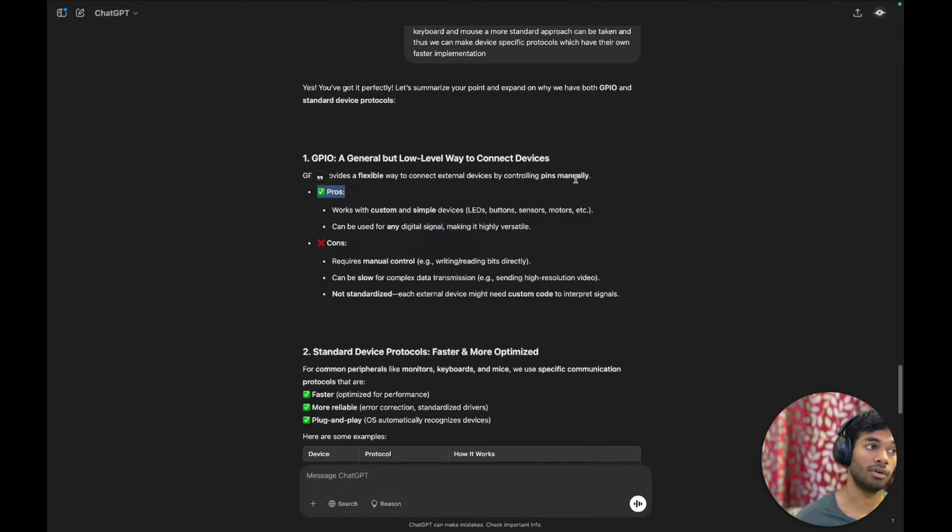Yeah, motors. I can use a GPIO which is embedded on a Raspberry Pi to control a motor, and that motor can be connected with a string which is wound around my doorknob, and whenever I click something, that GPIO will signal the motor to turn on, and that motor will rotate the knob for some specific time.